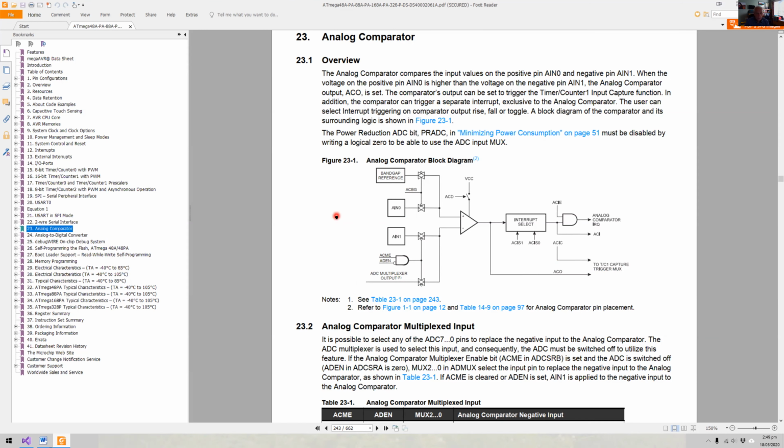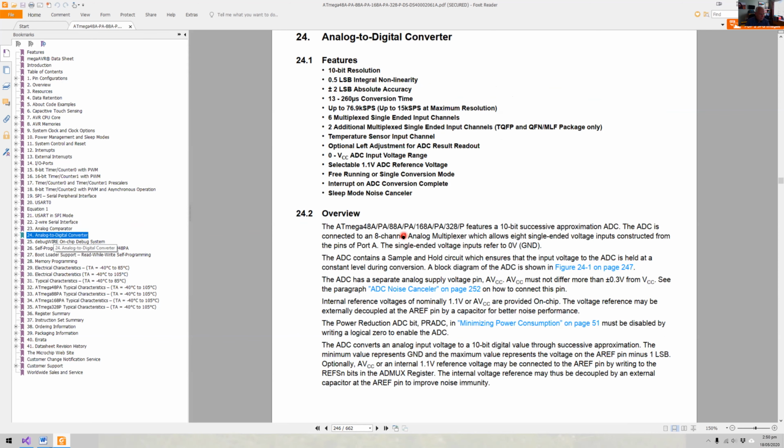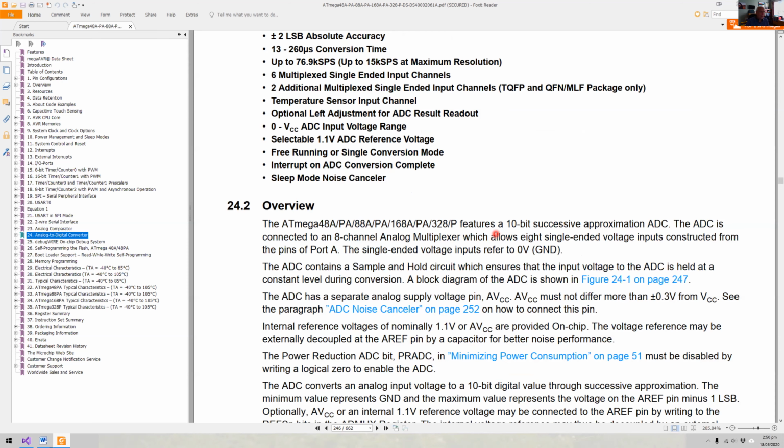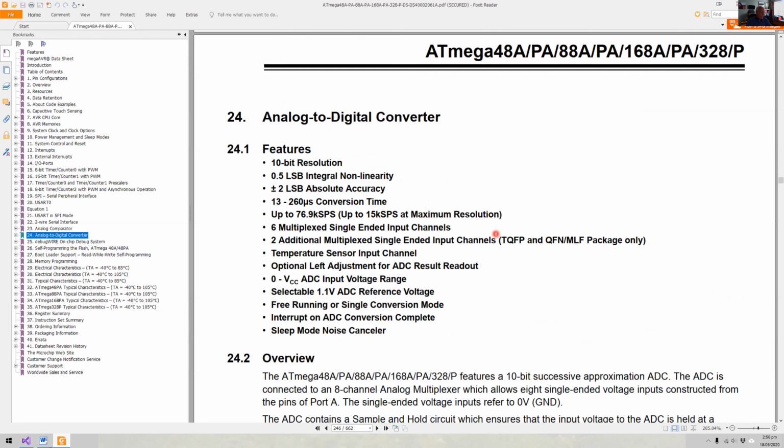We're not going to talk about it in the course, but I'll just bring it to your attention that there's actually a little comparator type op-amp built into this device that you can use to compare things. And actually then you can get it to trigger interrupts when things happen. So this again is a sort of an analog, but it's not like an analog switch. If the voltage goes above a certain level, hey, send me an interrupt. Interesting, but not what I'm going to talk about now in any detail. So let's go to the analog to digital converter. Let's see, what do we got here?